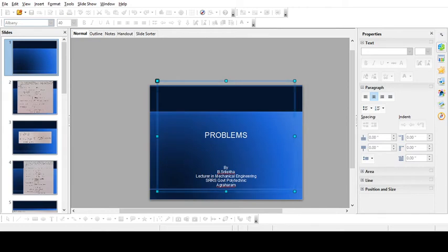Now, given diameter of the bar is D equal to 10 mm. The area of that cross section is pi d square by 4. Instead of D we substitute 10 mm, so we get pi into 10 square by 4, that is equal to 25 pi mm square. Given length of the bar is 350 mm and tensile load is equal to 15 kilonewtons. Tensile load means its length is increasing and its diameter is decreasing, right? So load is 15 into 10 to the power of 3 newtons.